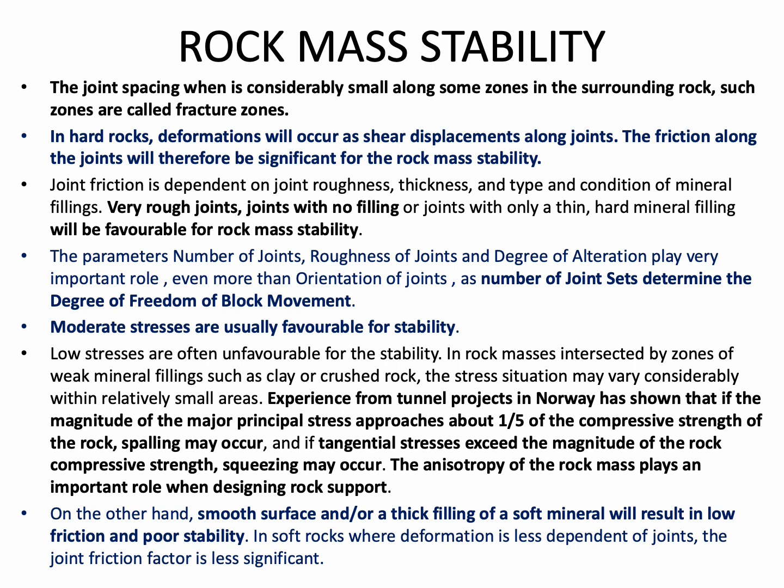Presence of moderate stresses is usually favorable for stability of the excavated section. Low stresses are often unfavorable for stability. In rock masses intersected by zones of weak mineral fillings such as clay or crushed rock, the stress situation may vary considerably within relatively small areas.